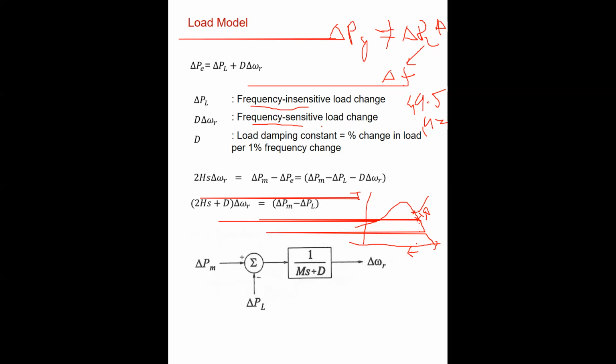If it is a motor load, then because of the drop in the frequency, the torque has changed. There is a torque increase. In fact, it is a positive torque basically, right? So that your mechanical load on the motor is constant. But the torque developed by the machine is now positive. So this positive torque is a positive power in the system. Wouldn't that just increase the speed of your motor?